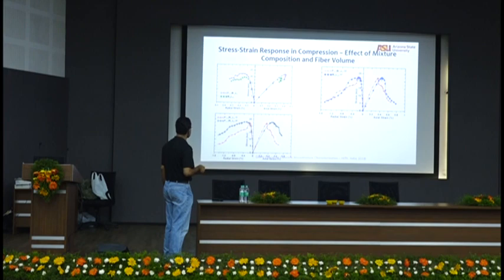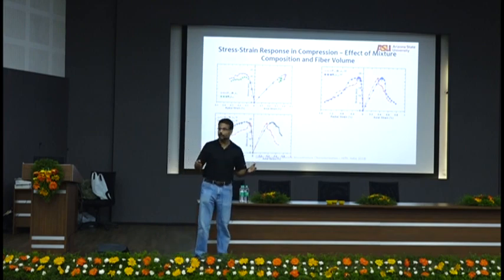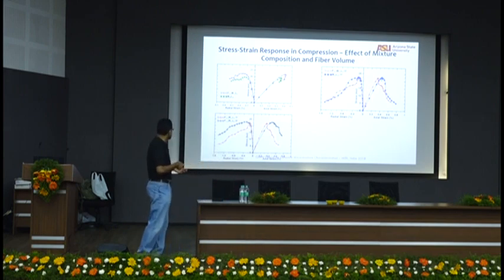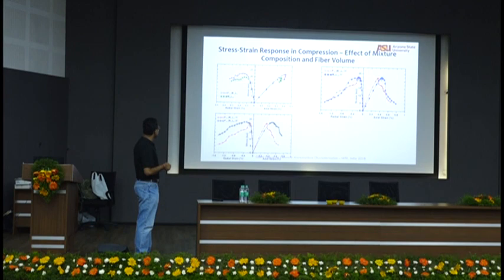And then look at the axial radial strain. You have a much higher strain, and again all these tests were done under radial strain control, so you can get very nice strain descriptions. You get a maximum radial strain at about 60-70% stress of about 0.3%. Very good radial strains.